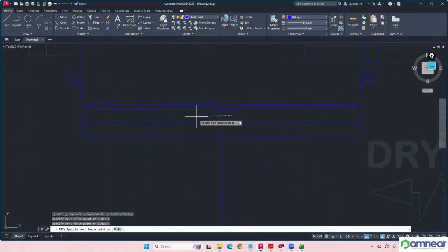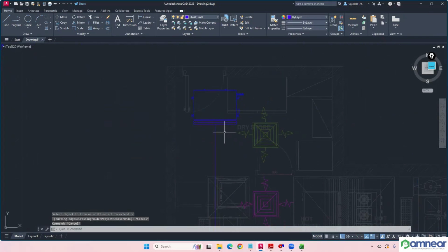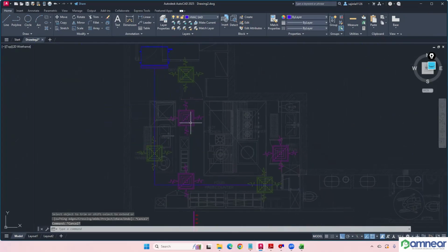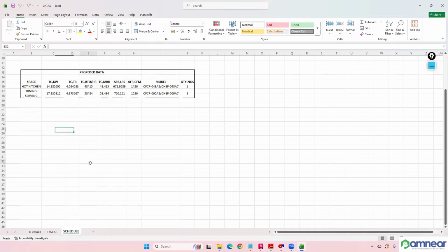Now for the duct, a few other things we have to select. We have to select the diffuser, then we have to size the duct, and only then can we make it like a two-dimensional layout. I placed my machine, I did the duct routing. Now duct sizing, before that the air terminal has to be selected. See, we need to do the calculations for that.